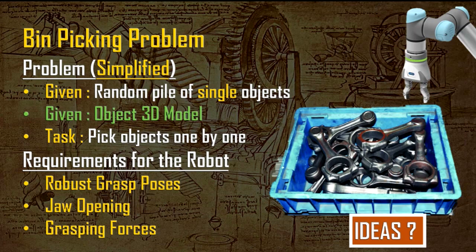Then in the actual real-case scenario, there will be a camera at the end effector through which we can determine the orientation of the object lying in the box. Since the robot is already trained to pick the object from a particular point, it will determine the orientation, and the end effector has a motor through which it can rotate. It will rotate to get the same orientation we trained it for, then pick the object from that same location.